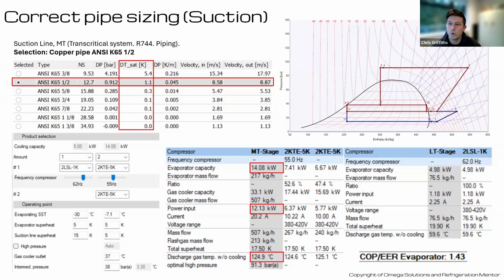This would be 1.1 Kelvin lower than that, which means we would be evaporating at -11.1. Or if we are evaporating at -6 Celsius, it'd be -7.1. And I always bother Trevor with this, but I don't know the conversion factor off the top of my head to Fahrenheit. I want to say it's around 14 or 12 Fahrenheit. I'm sure someone can correct me on that.